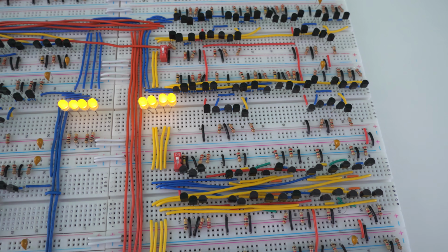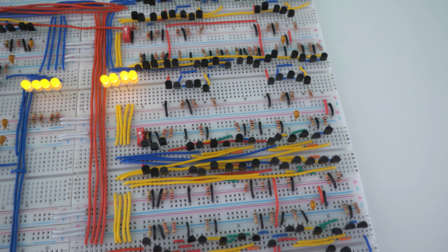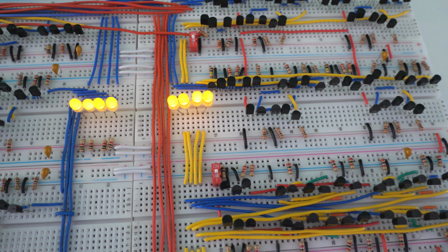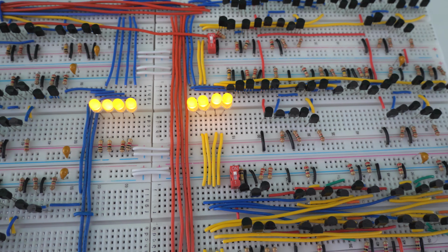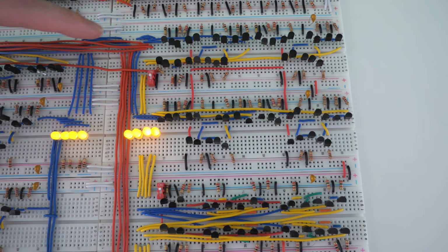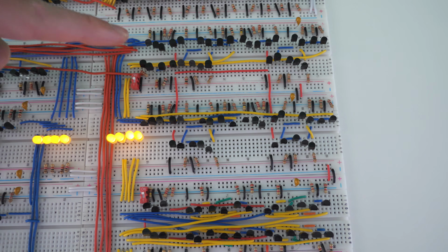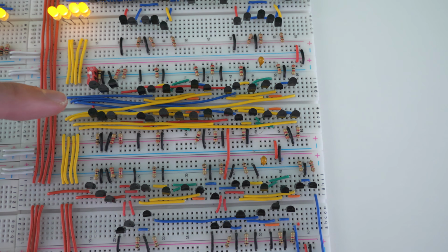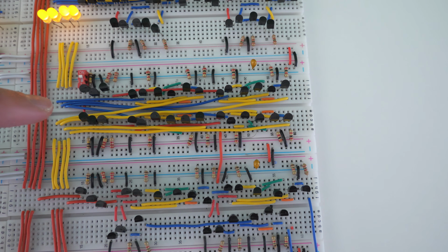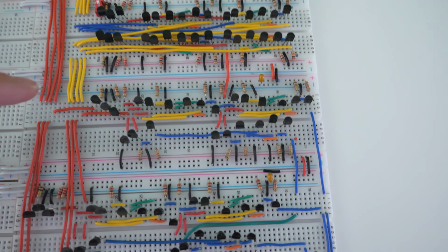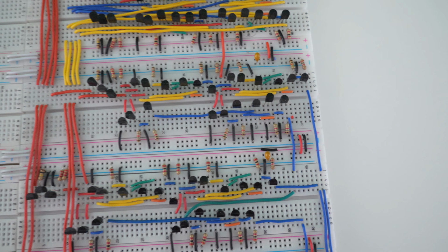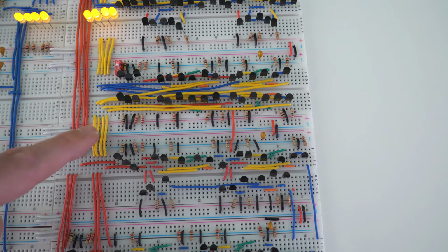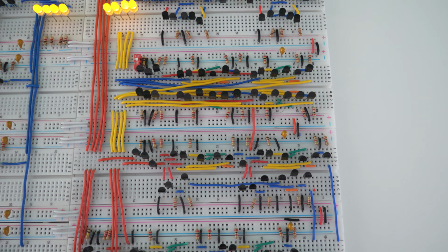And this is actually really nice because whenever we're trying to determine what the value of the ALU is, it's going to be A plus B or A minus B. So this is actually a really good way to display how the computer is working. And once the data comes into our B register and gets latched in our data flip-flops, it actually instantly gets sent to our exclusive OR gate board right here. If this is enabled, it will change the value, and if it's not enabled, it will just pass through this board and then go into the full adder part of our ALU. So if we look right here, we can see that we have register A and register B being fed into our ALU, which is what we want.